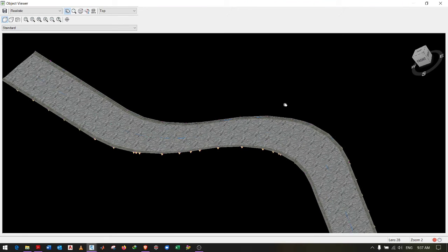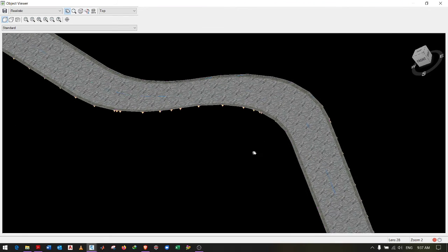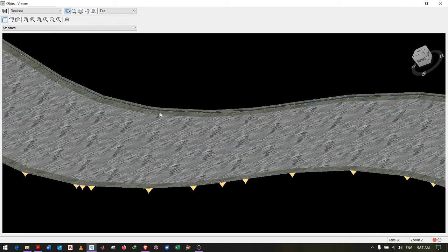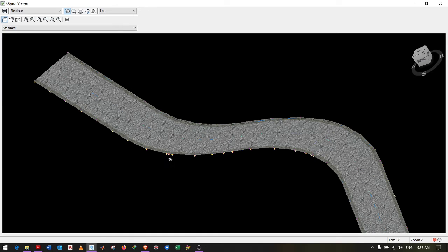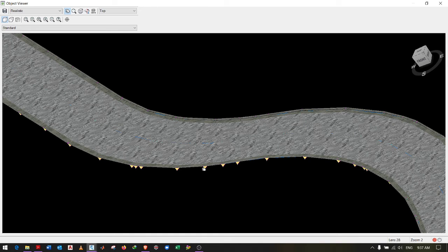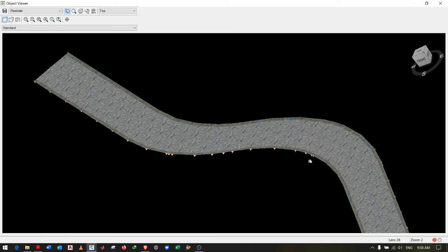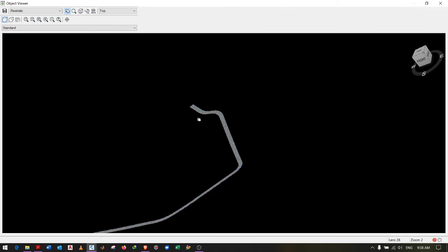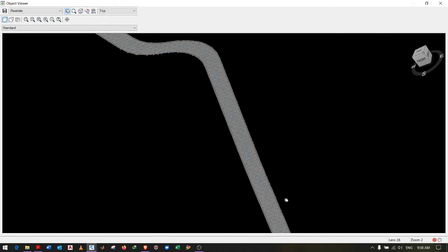So this is how, once you create a corridor, your surface would look. You can see a typical road over there which has this curved part and the main road, and these are the lines, if you remember, the sections every 50 feet, and these are part of the curves. If you remember, we have a curve over here and then here, so this is a reverse curve. So this is how your typical road corridor will look if you have created a surface.